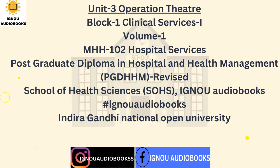It helps the surgical team, by creating a pleasant environment, and helps in maintaining the vital functions of the patient by providing an optimum comfortable environment. In order to provide clean air in sufficient quantity and to remove possible contaminants liberated by the surgical team and patient, it is universally recommended that the ventilation of the operation rooms should provide fresh air at comfortable temperature with adequate filtration or precipitation to eliminate dissemination of bacteria-laden dust.